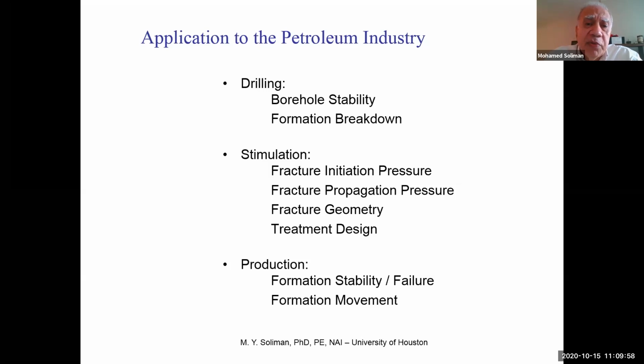Stimulation obviously is very important. Fracture initiation pressure, we are going to look at one equation here. We spend a little bit of time on it, because it's very important to understand. Then next week we'll talk more about the fracture propagation pressure. To initiate the fracture requires a certain pressure.